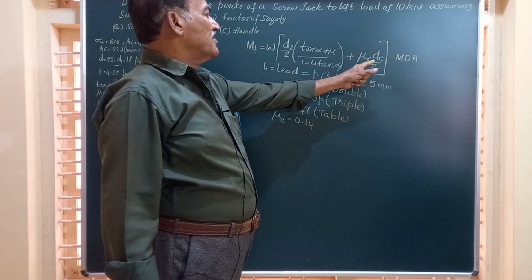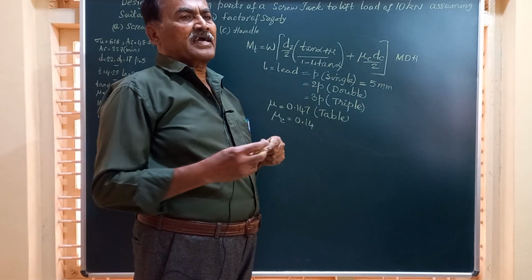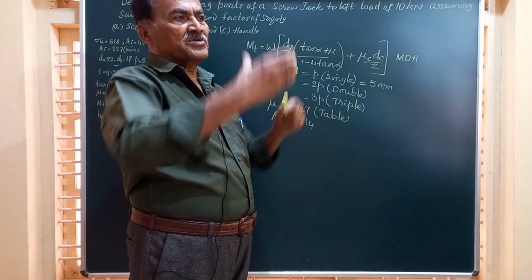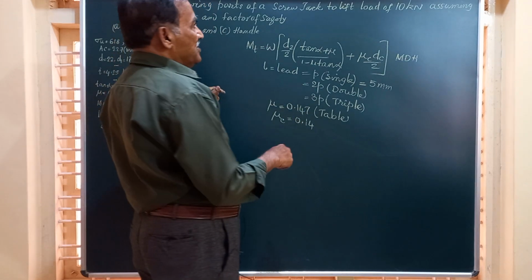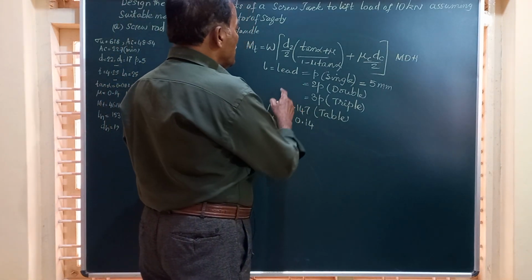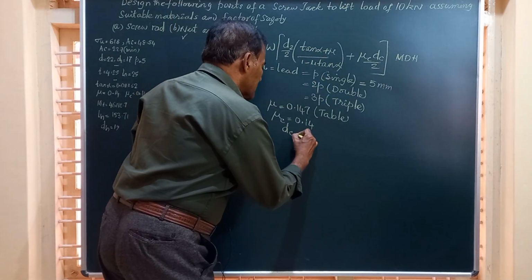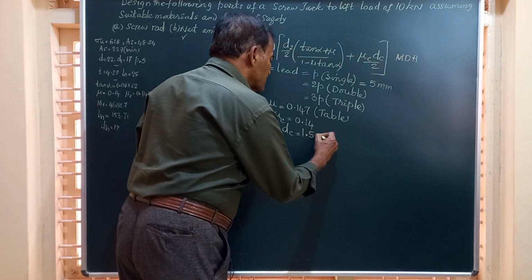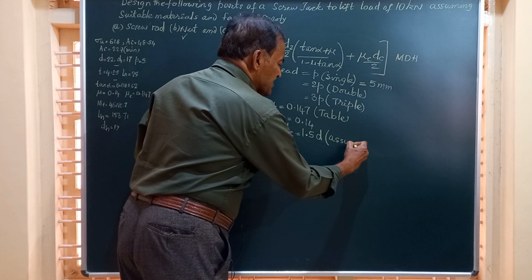And then friends, you are left with this DC. DC is the collar diameter. The collar is a part of the nut which rests on the base of the jack. Here this DC is approximated as 1.5 times d. It is only an assumption if nothing is given.